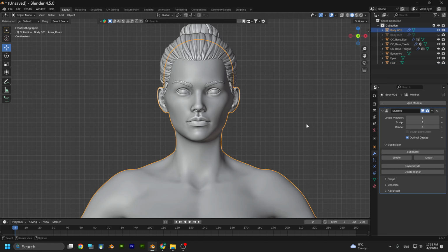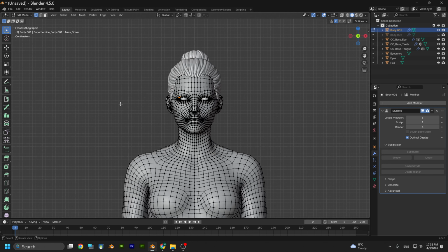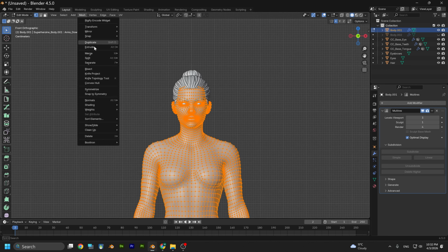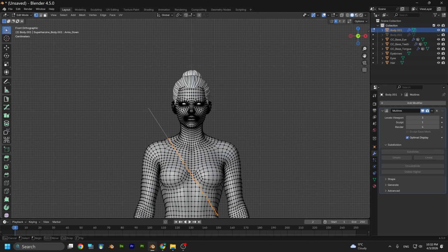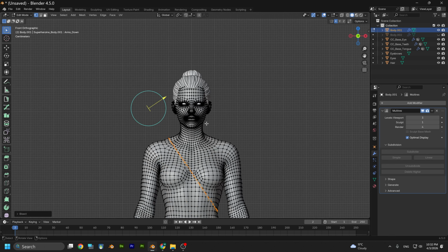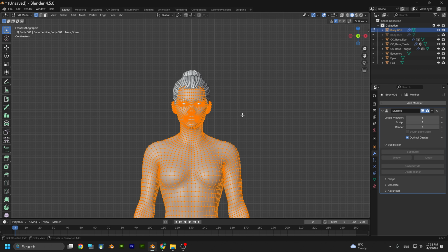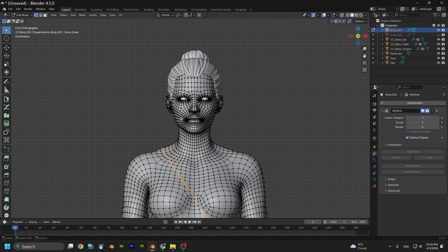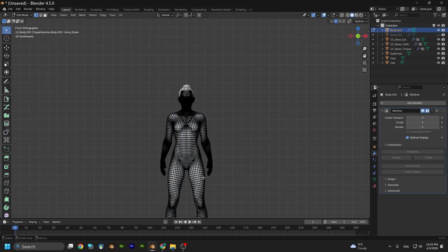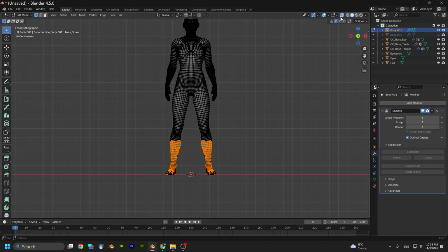And here now we need to cut what we need. So we're going to select the mesh and we're going to bisect from here like this. And now actually, no, we're going to leave it like this. Okay, now we select all mesh and we symmetrize to have the same one on the other side. And now we're going to delete, let me turn on the X-ray.